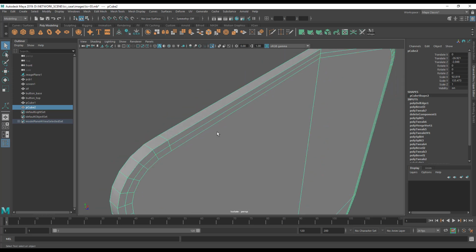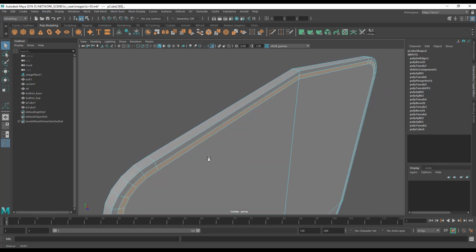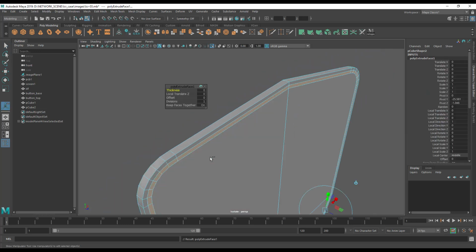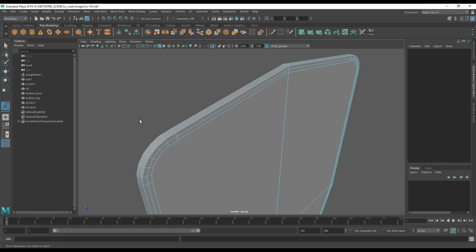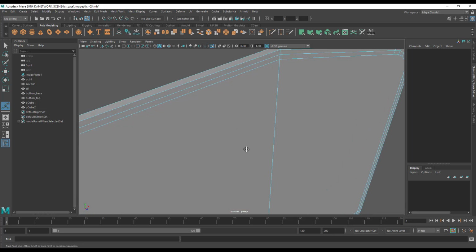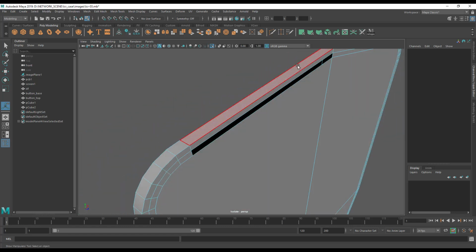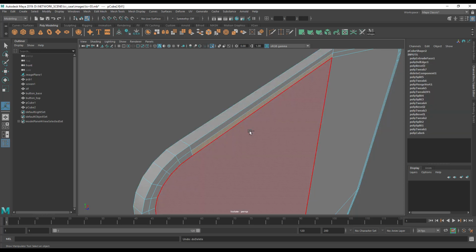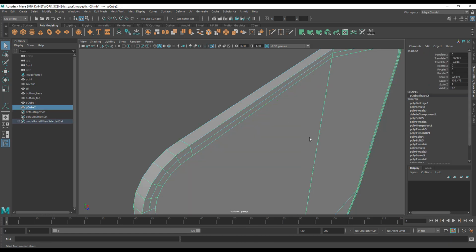If you get a dual extrusion, I've seen it happen to a lot of people, so I'll demonstrate it. You come in here and you click Control E for extrude or use a hotbox, and then you decide you don't want it. So you just click away and you can't see anything, you think it's absolutely fine. What you'll find is you'll often get sort of micro faces, faces that share the same point in space, and that would be non-manifold geometry, and that would be very bad.